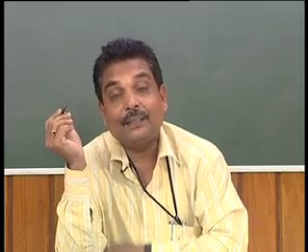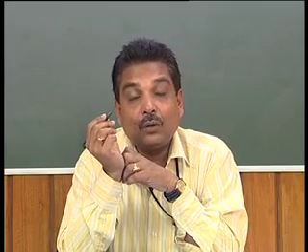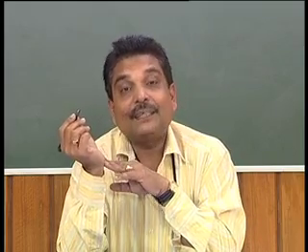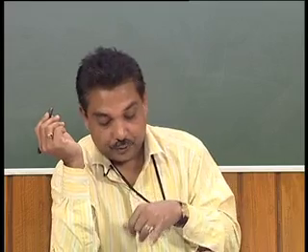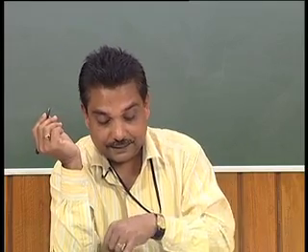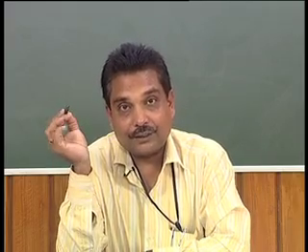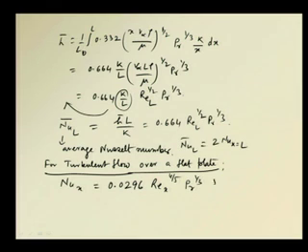There is one relationship, because we have to understand, higher the flow, higher will be the turbulence, higher the turbulence, better will be the heat transfer, and better heat transfer means higher will be the heat transfer coefficient. So, when we have a Nusselt number expression, it is expected to have a higher power for the Reynolds number. And here 5 into 10 to the power 5 is less than ReX, less than 10 to the power 7, and 0.6 is less than Prandtl and less than 60.